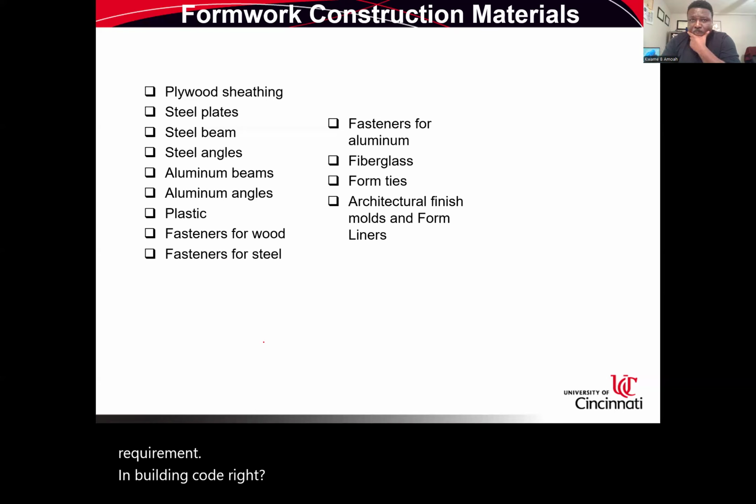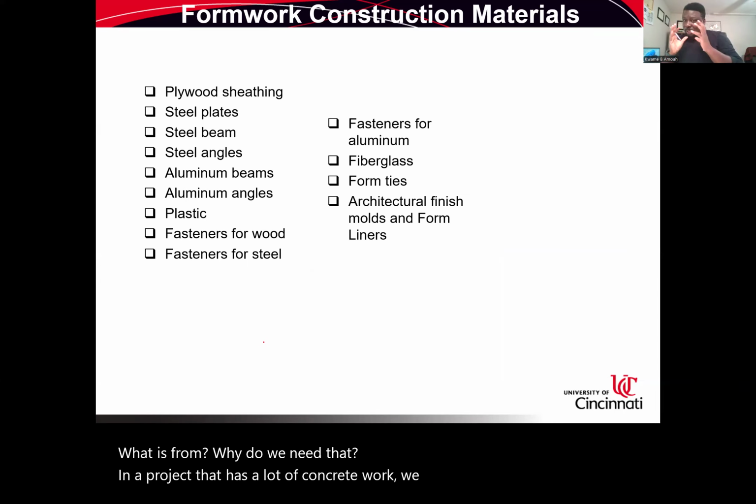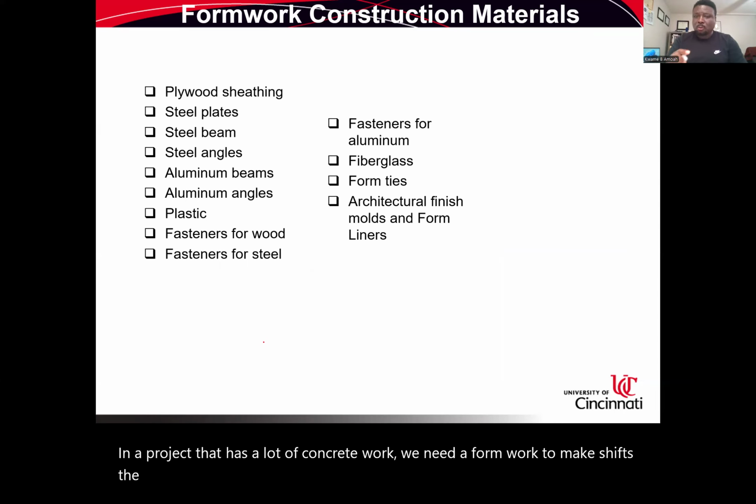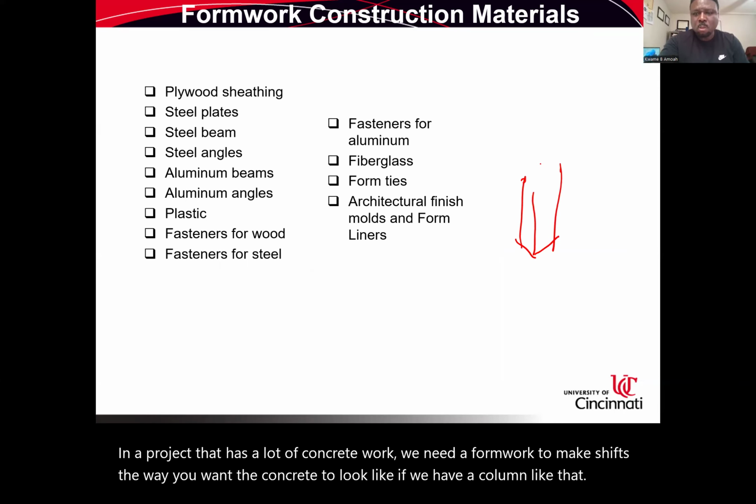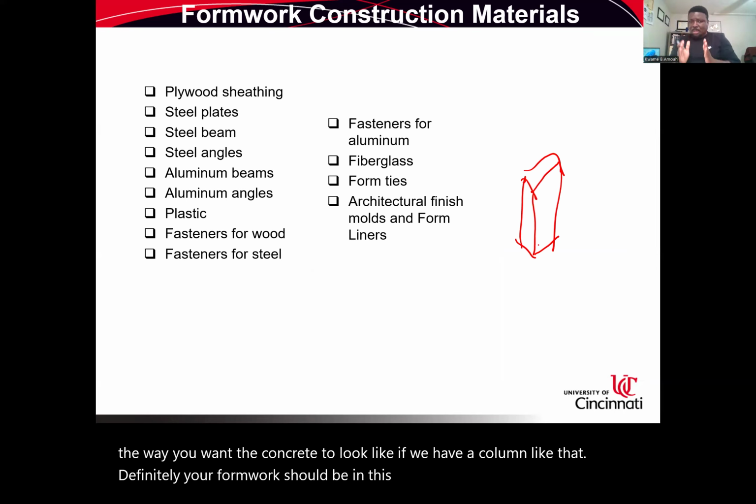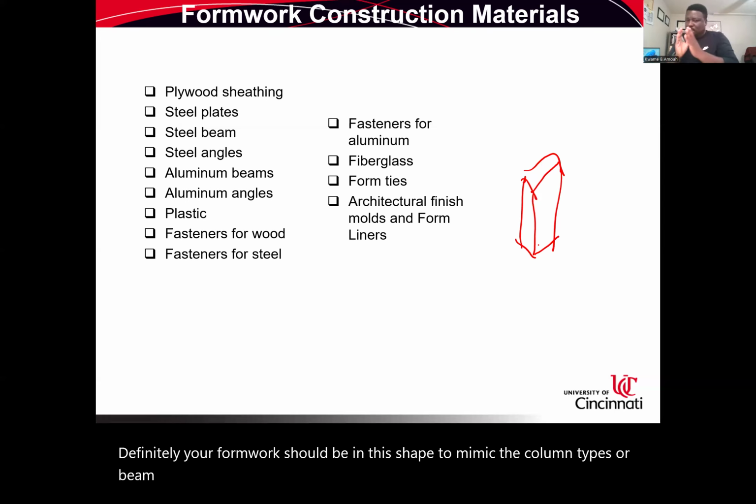Let's talk about formwork. What is formwork? Why do we need that in a project that has a lot of concrete work? We need formwork to make shapes the way you want the concrete to look. If we have a column like that, definitely your formwork should be in this shape to mimic the column types or beam types or slab types we have in those projects. And there can be different materials that are used for formwork.